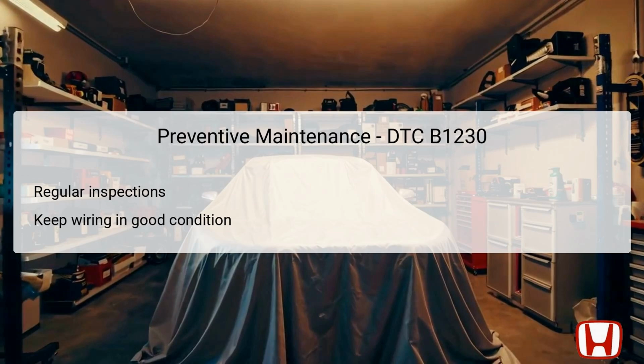To prevent future occurrences of DTC B1230 and ensure optimal functionality of the sunlight sensor circuit, regular inspections of the vehicle's wiring and connectors are recommended. Technicians should routinely check for signs of wear, frays, or corrosion that could lead to faults, as these issues can often go unnoticed until a DTC is triggered.